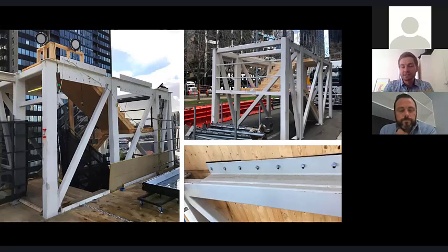And you can see the connection detail down on the right-hand corner there. So what we did there to accommodate the axial shortening of the timber in comparison to the movement expected of the steel is to have vertical slots to allow vertical translation. And this was already working towards the end of the construction of the timber structure. So that's just one example. Rob, do you want to chat about maybe just...